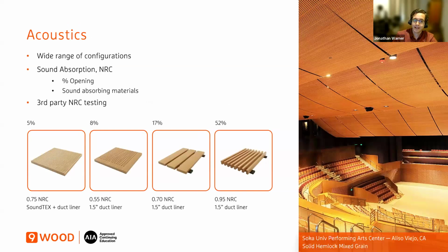Acoustics is a great way to have the beautiful wood ceiling work harder for your client, provide more value. And as I mentioned earlier, you don't need to have the word acoustic in the name to get good acoustics. It's really just driven by percent opening and sound absorbing materials. So the two factors that drive it. And so here are a variety of different products.